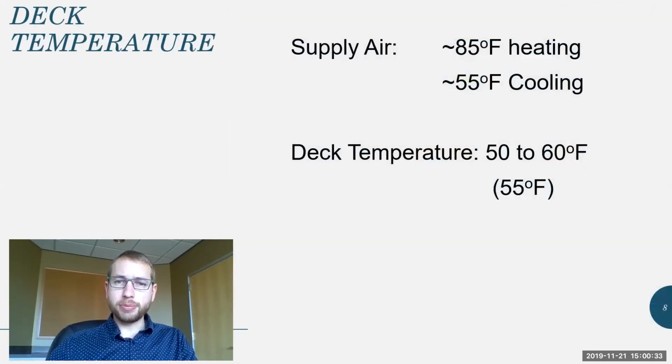So for supply air, if we're in heating mode, we want to bring in warm air to heat up the space. That might be about 85 degrees, maybe 55 degrees for cooling down the space. But the actual deck temperature doesn't vary all that much. It's going to be between 50 to 65, generally closer to about 55 degrees Fahrenheit in this particular climate.